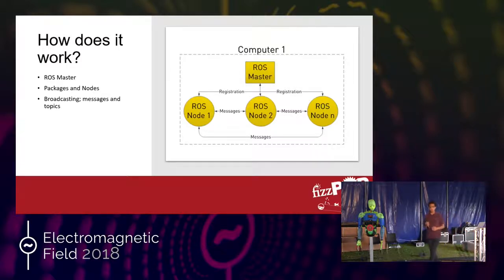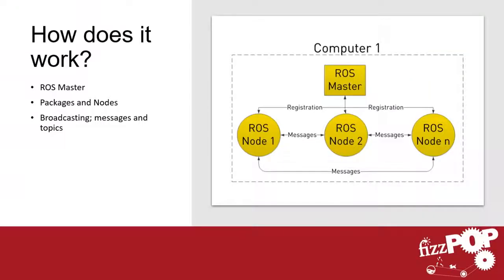So you normally have ROS itself running on your computer, and many different smaller packages or nodes will be operating the different parts of your robot. You'd have a node that is operating the cameras, picking up the image, and another node that is processing the image to output whatever features you're looking for, and another node that is maybe commanding your arm to reach out for something that you found in the image.